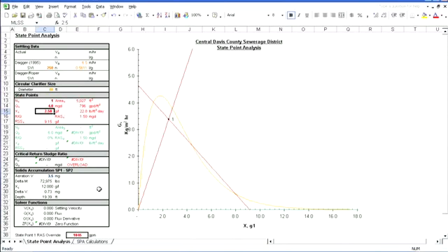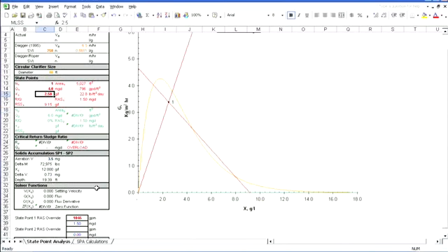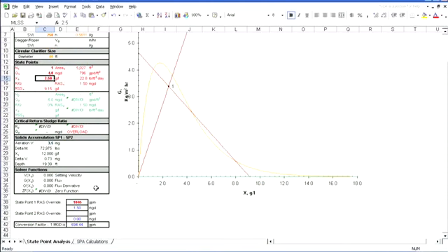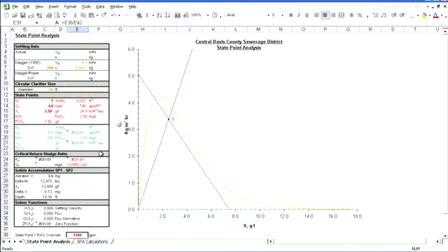So what can we do? Well, let's see. Say we actually have a little bit more capacity in our RAS pumps and can turn those up to 2 mgd. Well, does it help? Yep. As we discussed, increasing the RAS flow results in a steeper underflow rate line, and we're back in good shape. Good job, crisis averted.